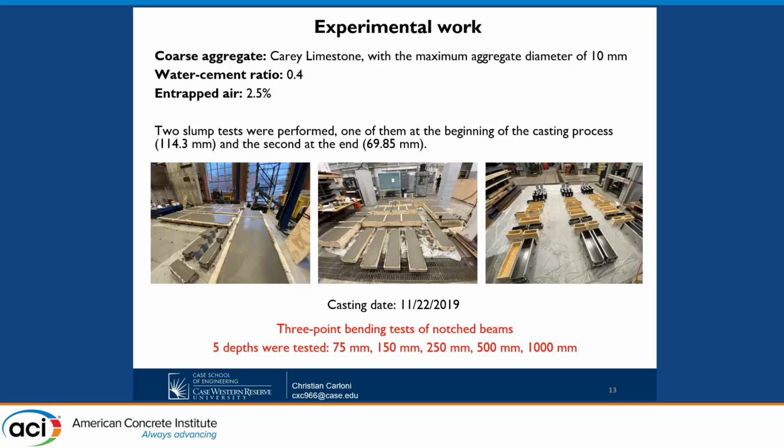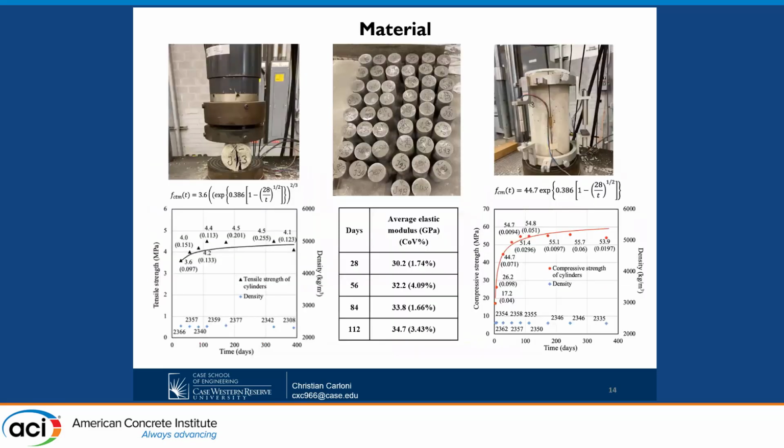This is all the casting. We basically occupied the entire lab for a month. So my chair was very happy about it. And we did all the casting, being very careful about making sure that the concrete was always covered with water. And we also cast a large amount of concrete cylinders, because we didn't want to test concrete right away. We wanted to let it mature enough that we were sure that the concrete was stable in terms of strength.